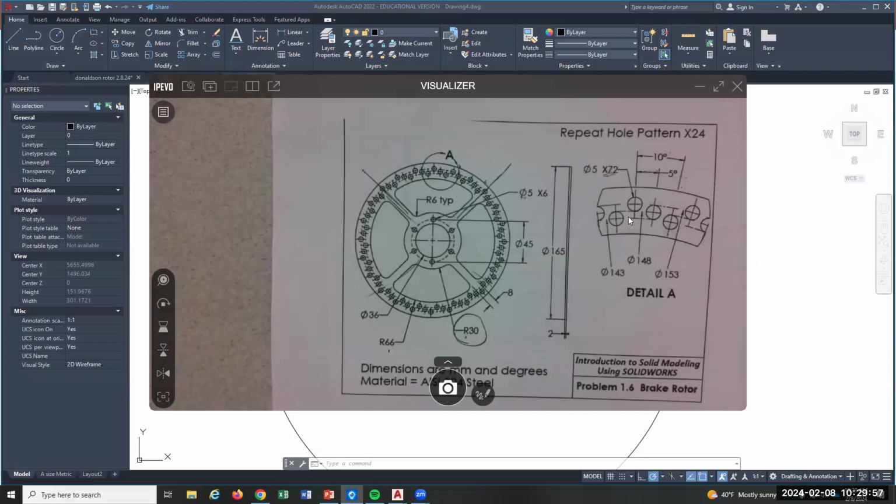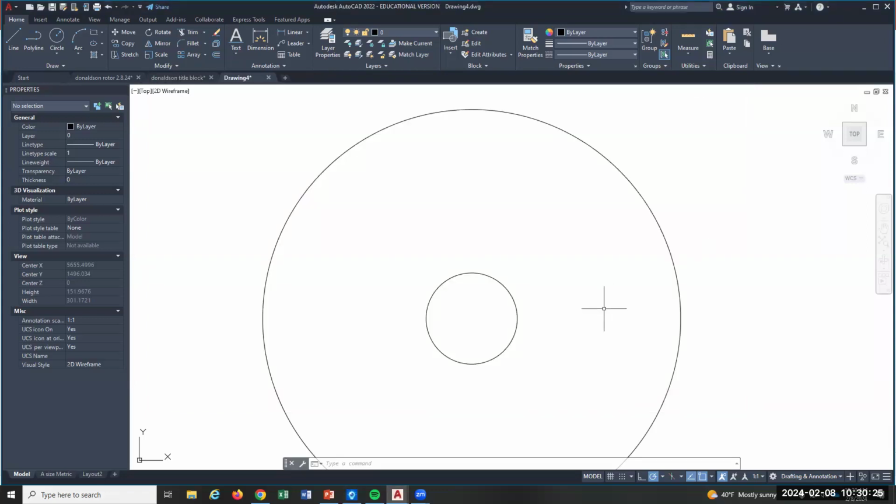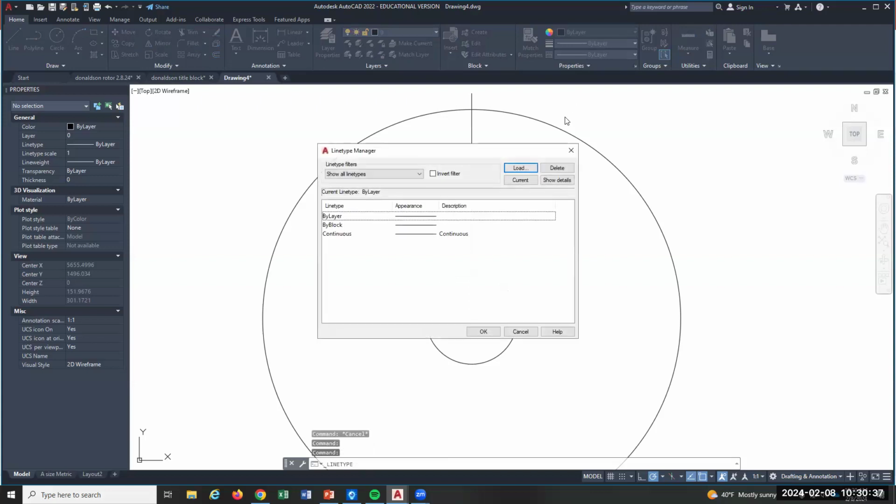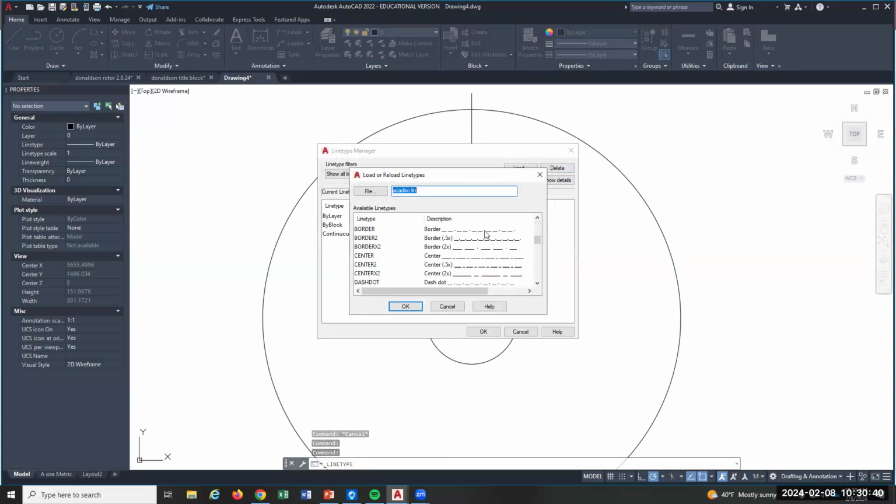So I'm going to need construction lines for each one of these, and they're 5 degrees off. I'm gonna array that too. Because I don't really like drawing that much. I like copying and stuff, right? So construction lines, and then I'll need these construction circles to get those intersections. And those circles are given here. Cool? So it's good to kind of come up with a strategy when you go to draw this creature. Oh, they're all line from the center up. So there's that first one, but I want it like in a center line. So I'm gonna go and load. Actually, I'll do a hidden line.